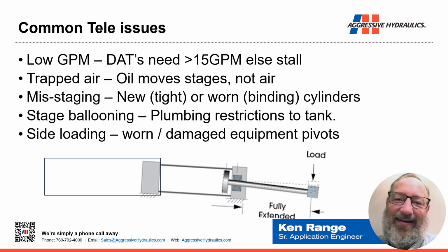Side loading. This is a term that's commonly used by customers that have an issue with their installation. If they have equipment that isn't square or straight, they will often ask for a cylinder that can handle side loading. There is no cylinder that can withstand side loading. The reason being is we have a simple lever arm situation.